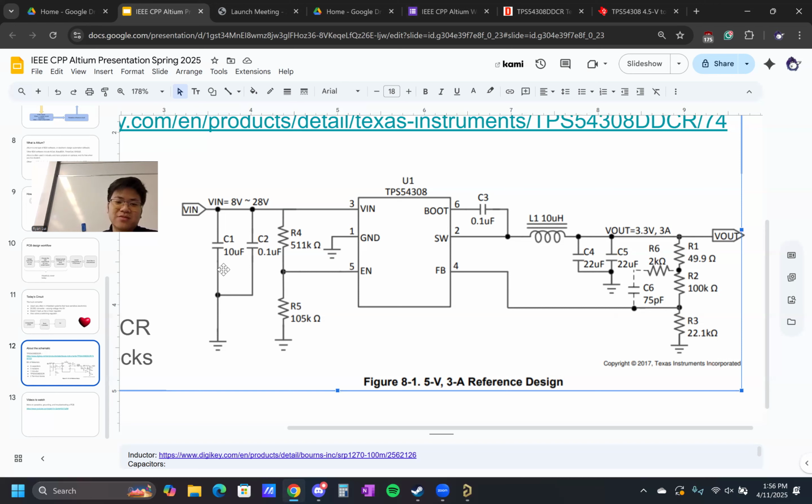We're using two different capacitor values here because, depending on their value, capacitors affect which frequencies get filtered out. You can think of it almost like an RC circuit, if you know about those RC filters. So C1, these 1 microfarad, 10 microfarad, are good for the lower frequencies.